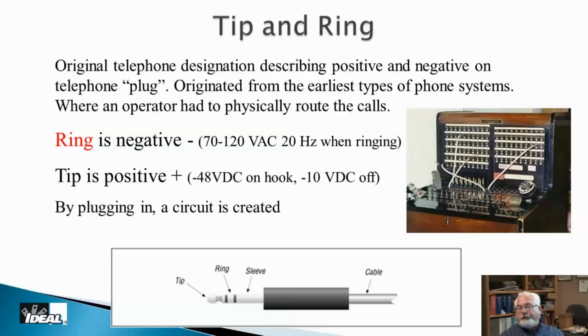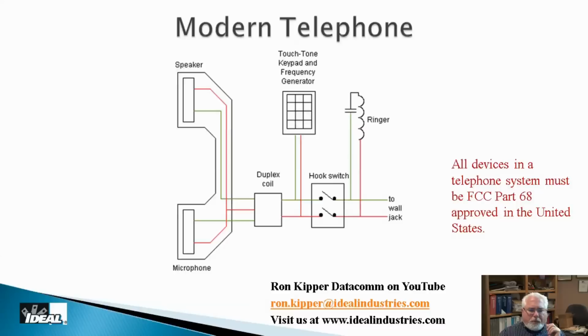But be careful, folks. There is some voltage present on that phone line, but specifically only when the phone is ringing. And it's one of the reasons why we would not want to plug a computer into a phone line accidentally, because if it rang and it was on the right pair, it could actually burn up a network interface card in a PC.